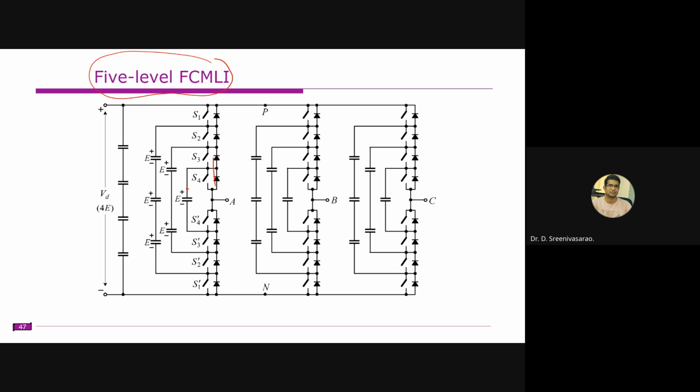Right. Because these capacitors are there, the capacitor will quickly take the energy and quickly store that energy. In the case of kinetic energy stored in the vehicles or wheels, it is half mv squared. So when the wheel velocity is reduced by half, the kinetic energy stored will be only 25%, so 75% will be dissipated. So we must act quickly to capture that energy. One of the quick ways to capture it is the supercapacitors. So first we store in the capacitors, and later we feed to the main battery, or else feed to the grid.